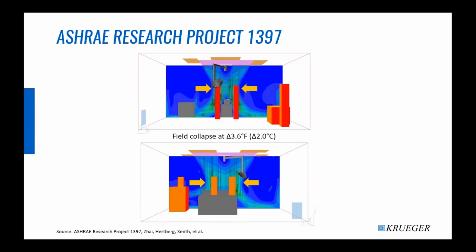So what can happen is you can see the airfield is collapsing here. And if you have contaminants that are flowing and cycling back up towards the ceiling, sometimes they can be pulled into this airstream. Because this is a relatively low velocity, but depending on the delta T, you'll actually create some acceleration here, and it can entrain some of those contaminants and pathogens back into the sterile field, flowing directly down on the OR table.